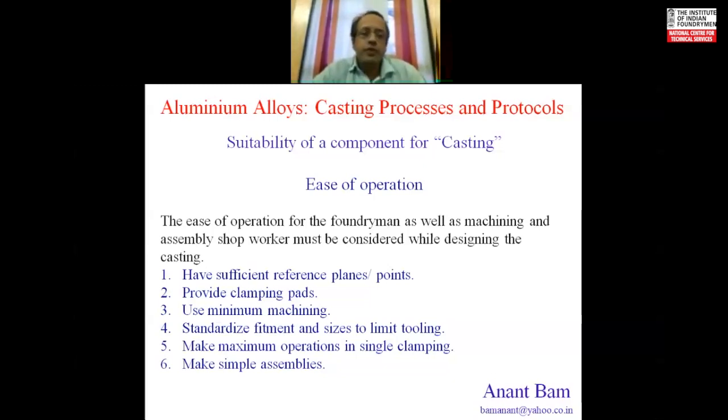So have sufficient reference planes, provide clamping pads, use minimum machining, standardized fitments and sizes to limit the tooling, make maximum operations in single clamping, make simple assemblies. All these things are applicable to the machining and assembly, but they have to be considered during the design stage itself.